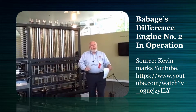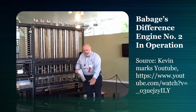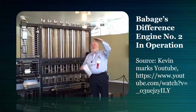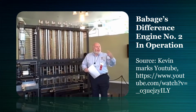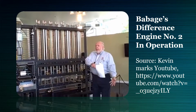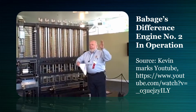Because during that part of the cycle, we're doing the same thing between the even and the odd next door. Its gear drops down, adds from one gear to the next, moves up a level, and resets the even. And then moves up again, so it's disengaged, so we can go back to doing the odds again. So a complete cycle is odd is added to even, odd is reset, disengage. The other side does even is added to odd, even is reset, disengage, and back and forth we go.